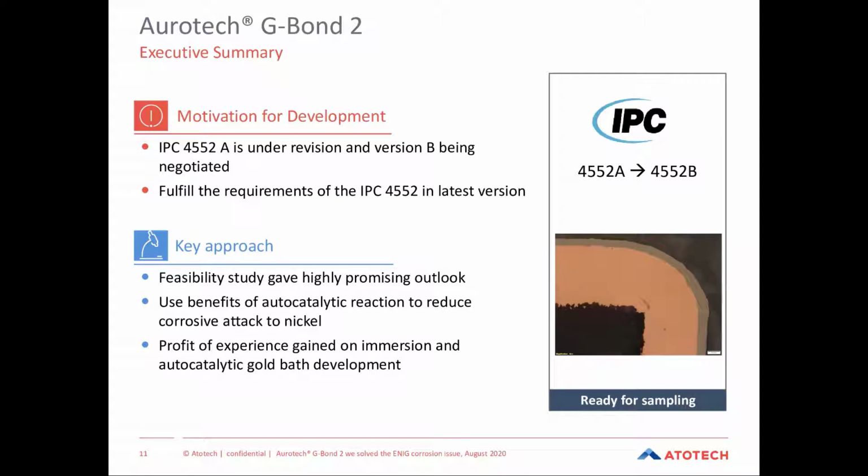And version B, which is currently being negotiated and under preparation and will hopefully be released soon, will then further describe and define when you have to look for corrosion, how many areas you have to inspect, and really distinguish which type of corrosion will be critical and which can be pass-fail criteria for a PCB to decide if it can be accepted or not.